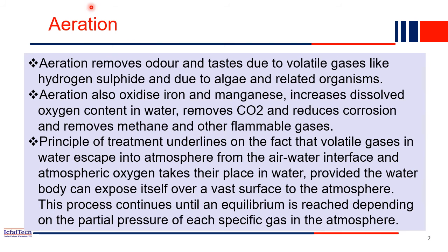So aeration is a process. In the next slide I'll be explaining how we actually do the aeration. But basically, aeration is a process in which we are removing these toxic gases from the water, and we are adding more oxygen content into the water.